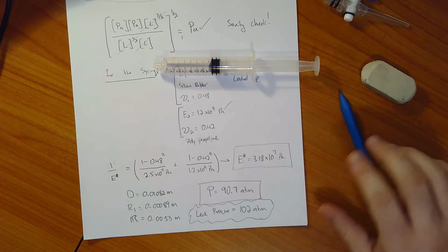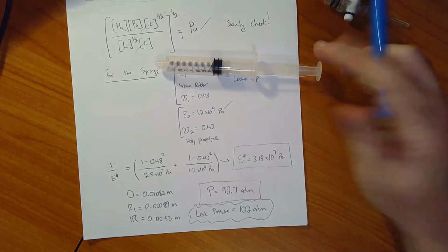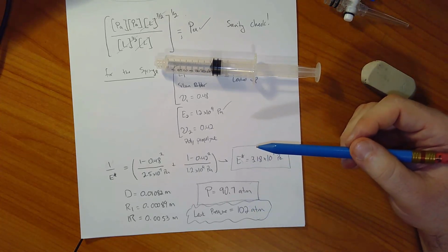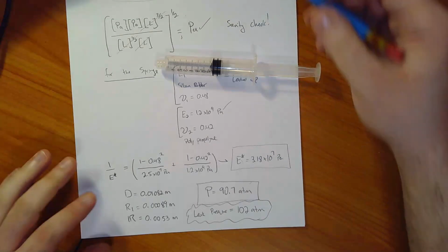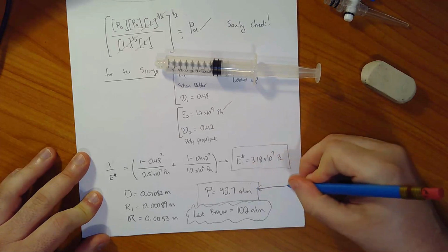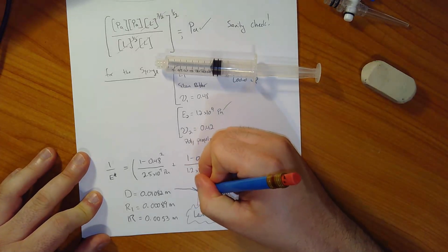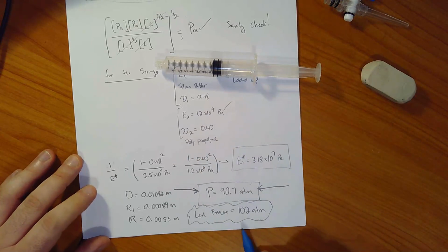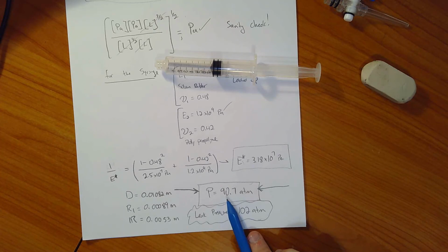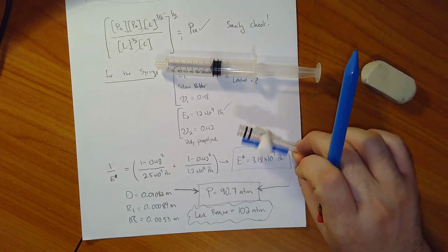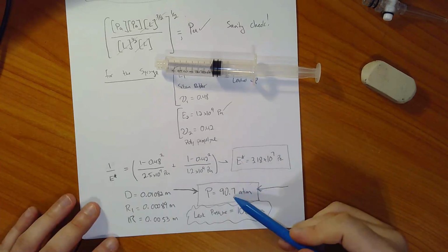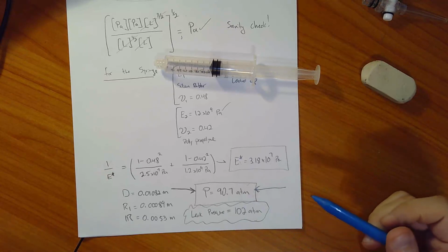And really the point of this is that this was a bounding analysis, right? So this pressure is lower than the actual leak pressure. And so barring any other information about the O-rings other than just doing this analysis, I would actually set the leak pressure here, and of course with a factor of safety. But I'd be pretty well convinced that if I don't have hydrostatic pressure at the burette stopcock interface that exceeds this value, it's not going to leak. It is a lower bound because the actual value is a little bit higher.